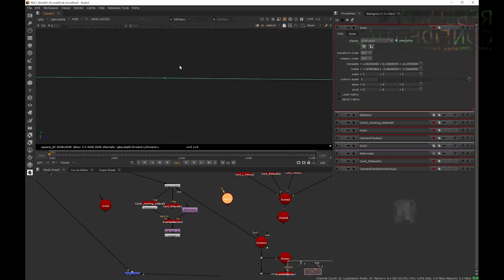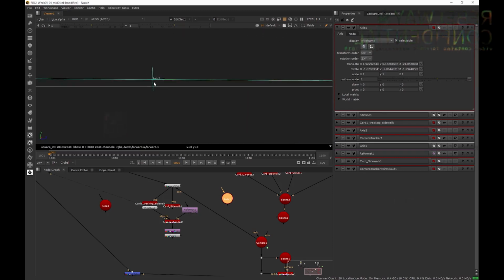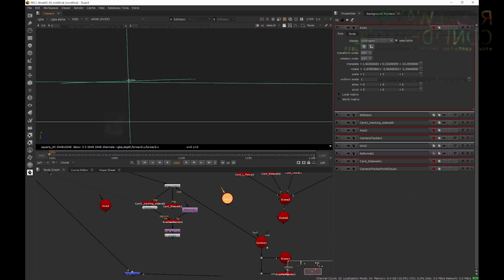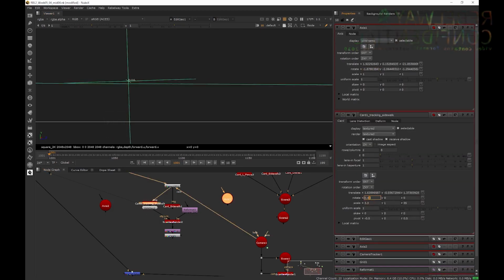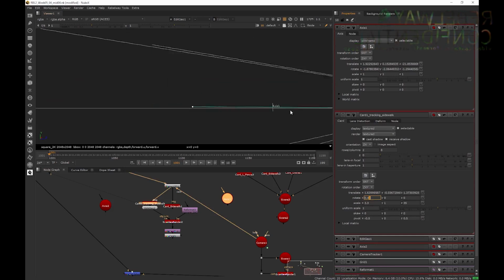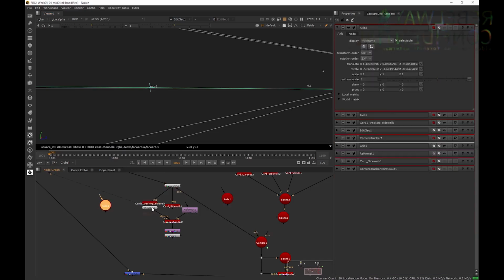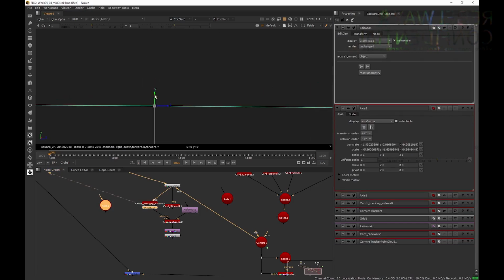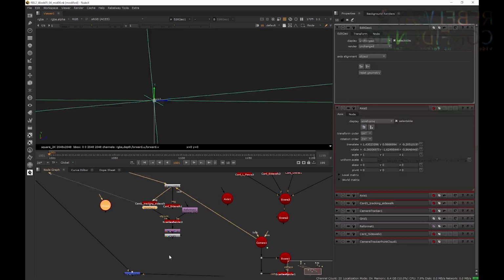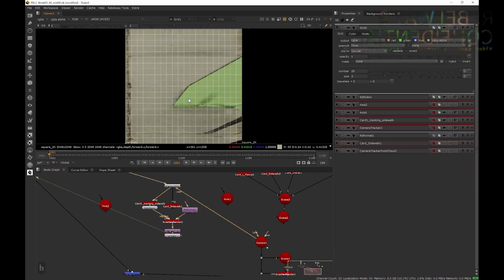We'll go into our left side view and we'll try to compare with that, and we can see that this is still pretty darn closely aligned. Maybe if we really wanted to, we could rotate this just a touch more in X to get that even closer. But as we rotate there, we are going to want to make sure that we didn't mess up our alignment with axis 2. It is a little bit annoying to work like this, but it's the best Nuke has. Really, you should be doing this in a modeling program, but we're just trying to keep it all in Nuke.